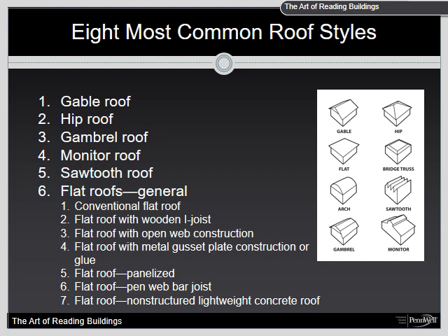This design is popular due to its ability to provide the advantages of a sloped roof for rain and snow runoff while also providing maximum headroom in the area below the roof. The most popular use of this roof design is found on barns on many farms in this country, but it is also used on some residential and commercial buildings. Although a gambrel roof can be constructed from either conventional or lightweight construction methods, most of these roofs have been constructed using conventional construction.